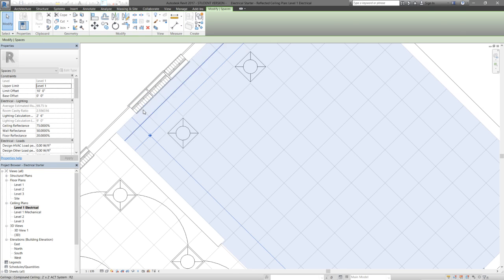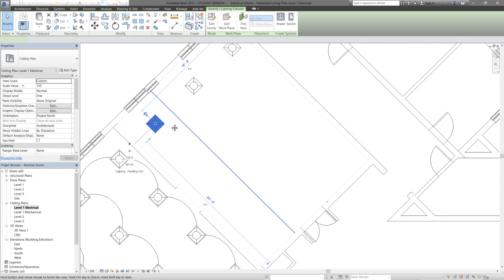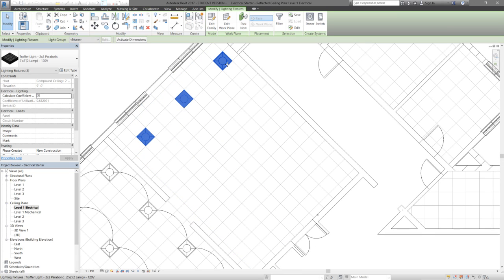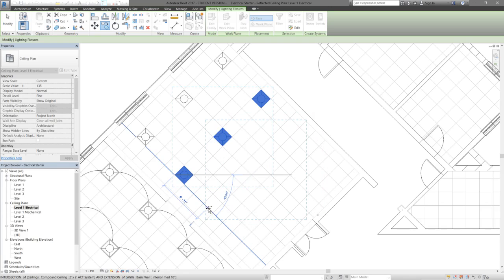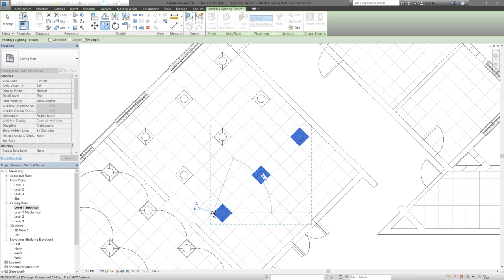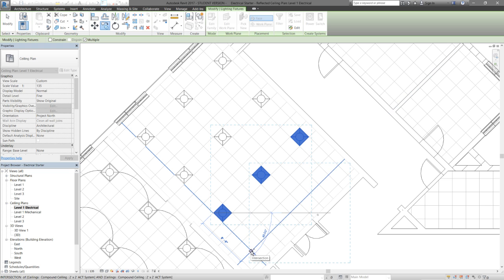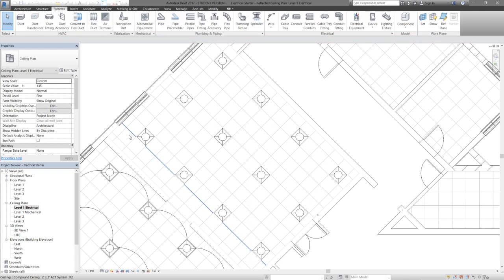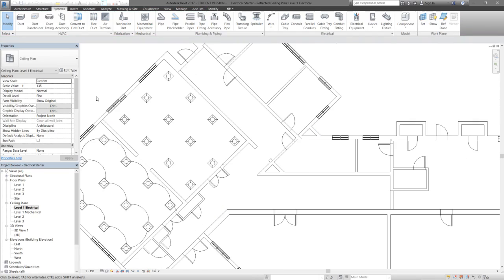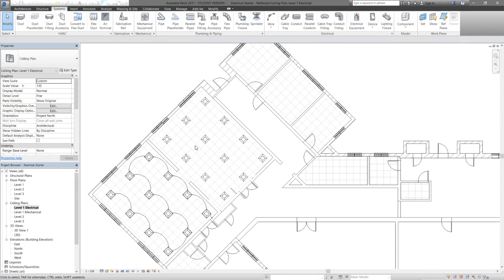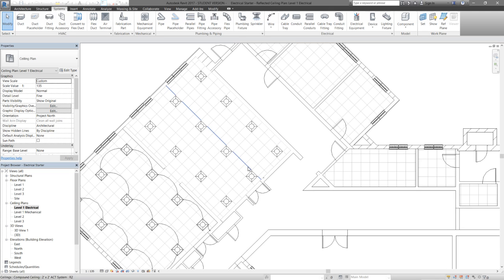that is 69. And then if I copy this now, just a couple times here, and I'm just trying to keep my spacing consistent by counting my ceiling grid. So now I'm at about 280 lux, so we're good there. So our room has lights, has a light switch. Our last step is the wire.